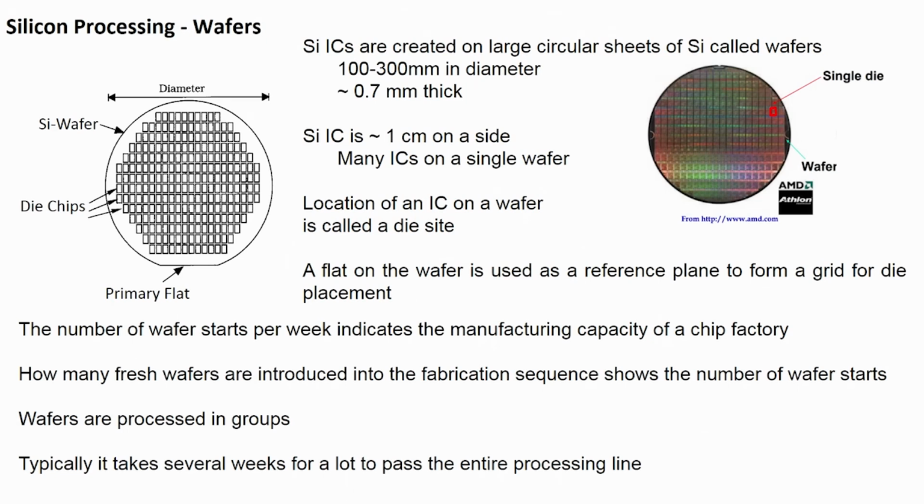This is the last slide for this particular lecture. What we have seen today is very important, even though it is very basic: what kind of substrates there are, how we can use them, and how they are manufactured, which we will see later on. We have already seen one or two examples, where we can make interdigital electrodes or piezoresistive microcantilevers. We have also seen types of substrate: silicon, oxidized silicon, silicon sizes, silicon orientation, primary flat and secondary flat, and how we can identify N type or P type, 100 or 111.